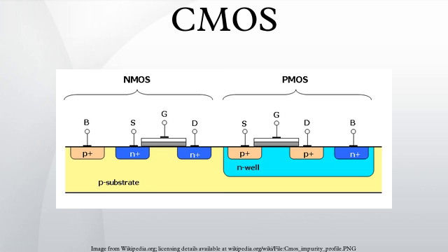Multi-threshold CMOS, now available from foundries, is one approach to managing leakage power. With MT-CMOS, high VTH transistors are used when switching speed is not critical, while low VTH transistors are used in speed-sensitive paths. Further technology advances that use even thinner gate dielectrics have an additional leakage component because of current tunneling through the extremely thin gate dielectric.